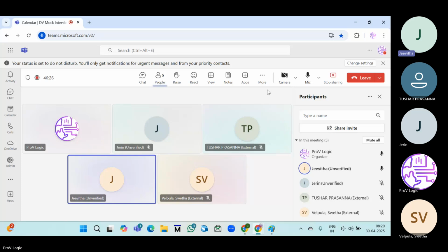Whereas in asynchronous reset, the reset will happen without depending on the clock. We will specify always @(posedge clock or posedge reset). So in the always block, we need to mention reset. Then it is asynchronous. If we don't mention it, it is synchronous, and it will change with respect to the clock.